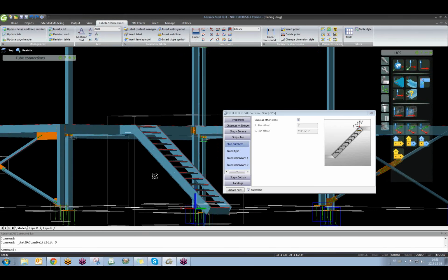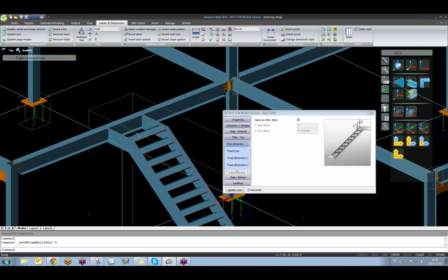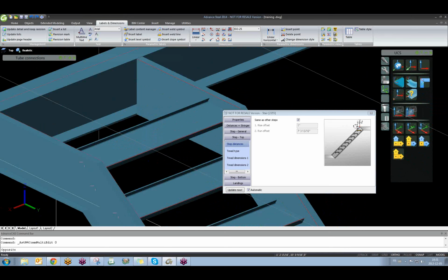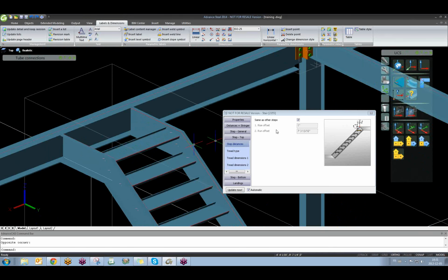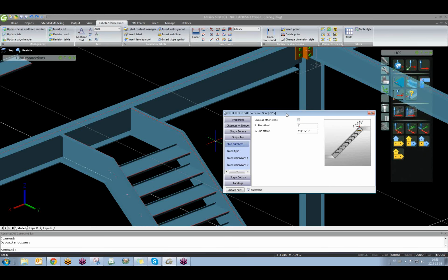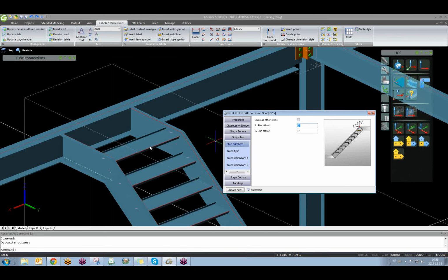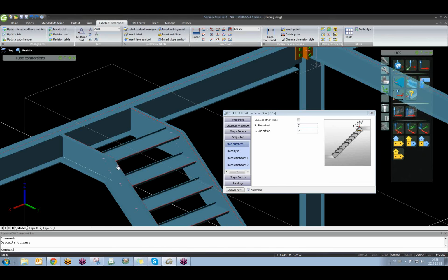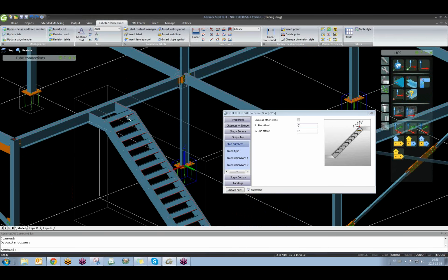what you wanted to see? I don't know. I'm still trying to decide. Is anybody following where I was going with that? I think I get what you're talking about. Your top nosing should be equal with that floor height, top of steel, whatever's going to be on top of that floor. Right. 1.25 inch grating, whatever. Your top nosing should be equal to that. You shouldn't have a 1 inch rise at your landing.